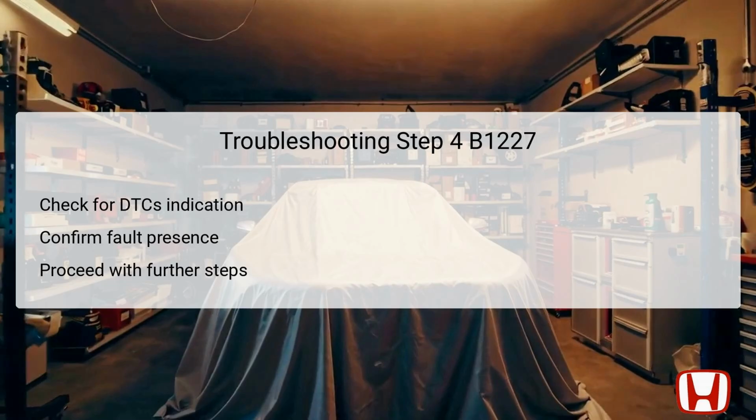As a technician, you must proceed to investigate further components and circuits linked to this sensor. If, conversely, no DTCs are present, it may indicate an intermittent failure, which commonly arises due to loose wires or poor connections. Understanding this differentiation is vital as it guides the technician toward the right corrective actions, whether that means replacing the sensor or repairing wiring failures.